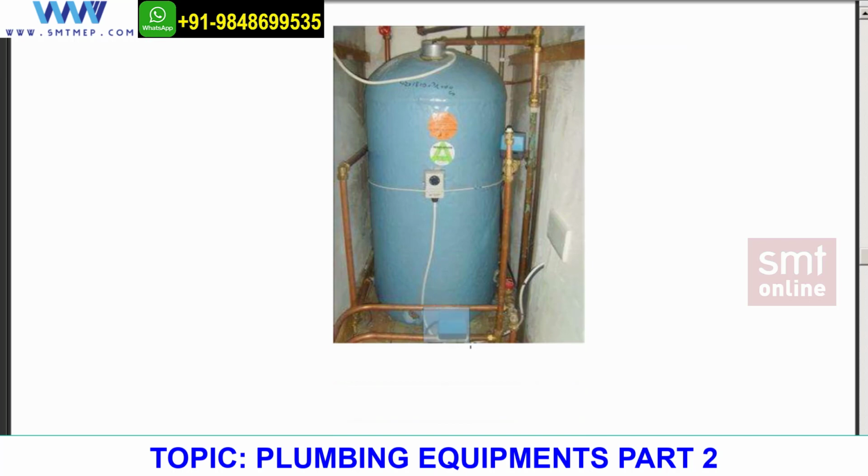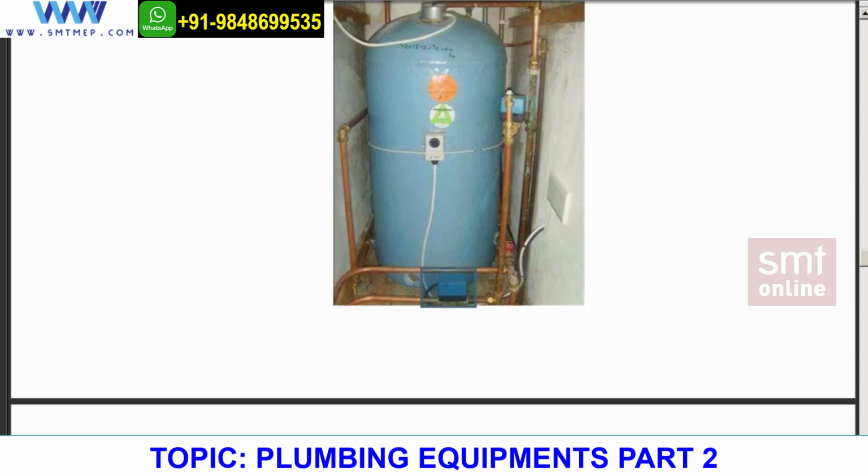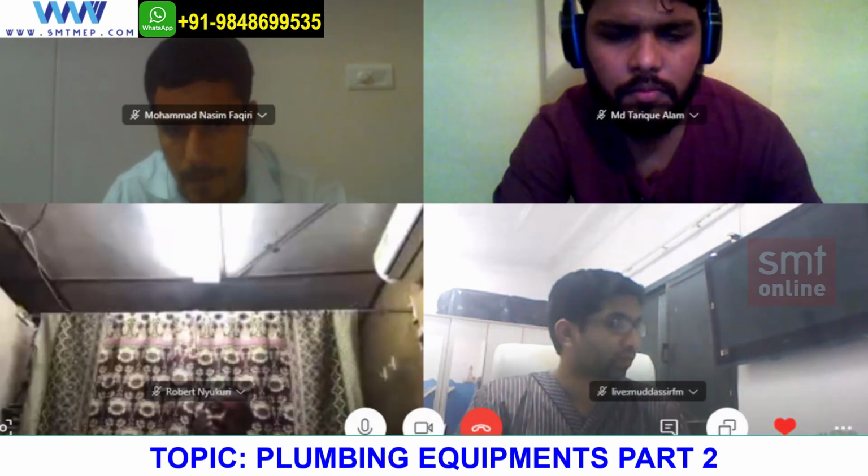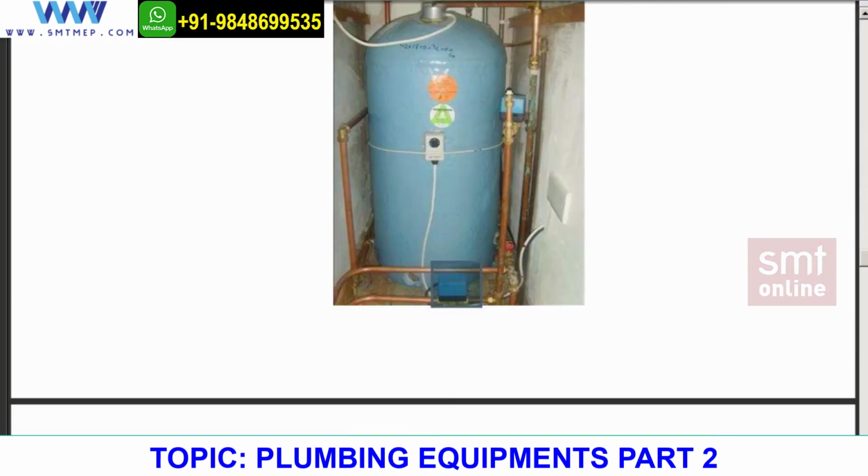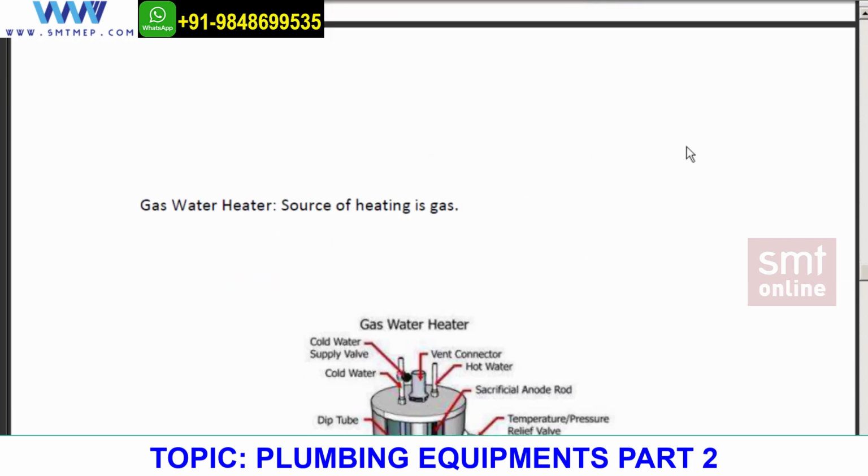And you can see online over here, I do have two circulating pumps. Now why? First of all, is this a circulating pump? Yes, it is. So I do require two circulating pumps, one for the hot water supply and one for the hot water return. Getting this? Because in the supply I need to have one hot water circulating pump. If there is none, then it will be returning back, right? In this manner. So two circulating pumps.